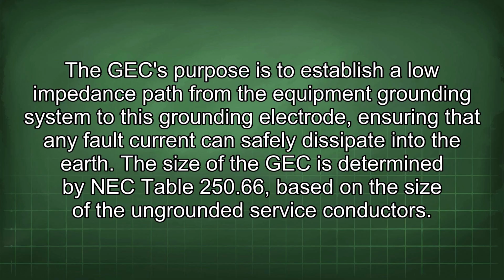The size of the GEC is determined by NEC Table 250.66, based on the size of the ungrounded service conductors.